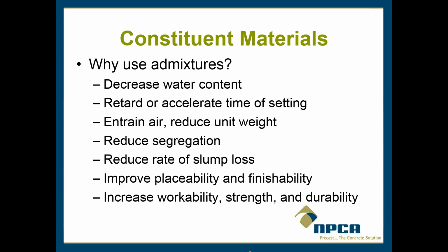So as Claude just said, why do we exceed that perfect, quote unquote, perfect water to cement ratio? Why do we exceed it? We exceed it because otherwise it's a pain in the behind to place your concrete. So this is one way that you can achieve a more workable, flowable mix without increasing your water to cement ratio to some ridiculous number and having really weak concrete. So also entrain air, reduce the unit weight, try to prevent segregation, improve your workability and strength.